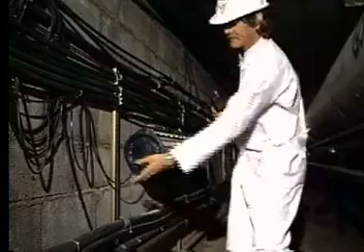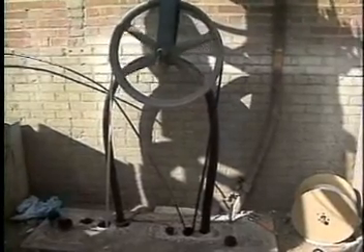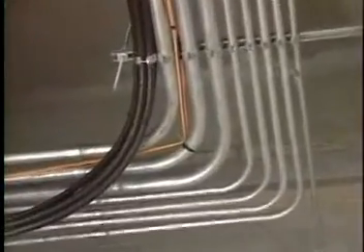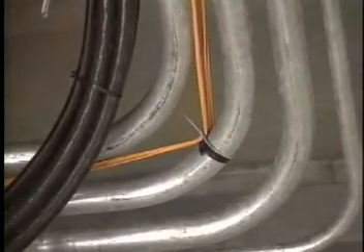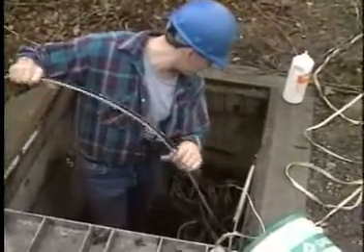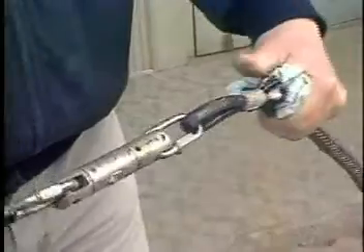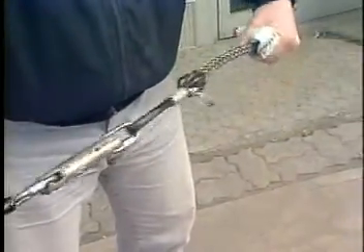Whatever the placement type, whatever the cable type, the 2 critical factors for a successful installation are cable bend radius and pulling tension. Exceeding manufacturer's specifications on either of these factors may damage or impair the quality of the optical fibers within the cable. Failure may not be immediate, but may show up days or even years later. Most cable installations are designed to provide 30 years of service, a lifetime obtainable only when proper installation techniques are employed using products designed for the application.